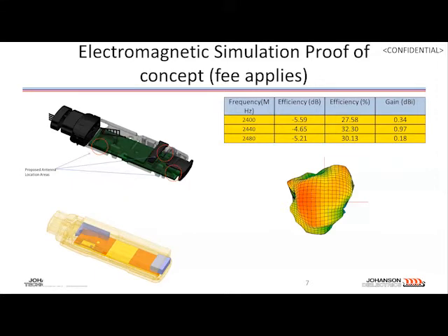either mounted or unmounted antenna PCB. We recommend, or actually require, you to have all the components mounted, soldered, batteries connected, and any USB connector near it. All that influences the final fine tuning of the antenna. All chip antennas need some sort of fine inductor, capacitor, or component tuning, and we provide that service to define those